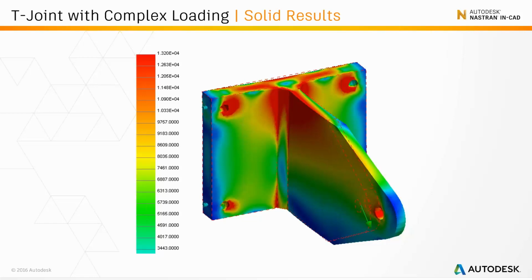So what's the best way of using a solid? Well, really we should be approaching using solids in much the same way as we've looked at using shells. And that is to use the solids to give us further information about the loads that are being passed between those two plates there, rather than using the loads to determine the stress on the welds themselves.